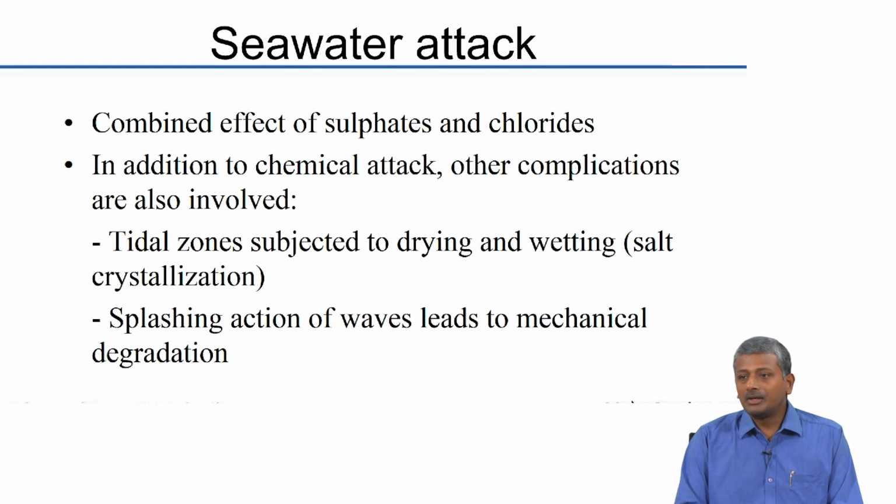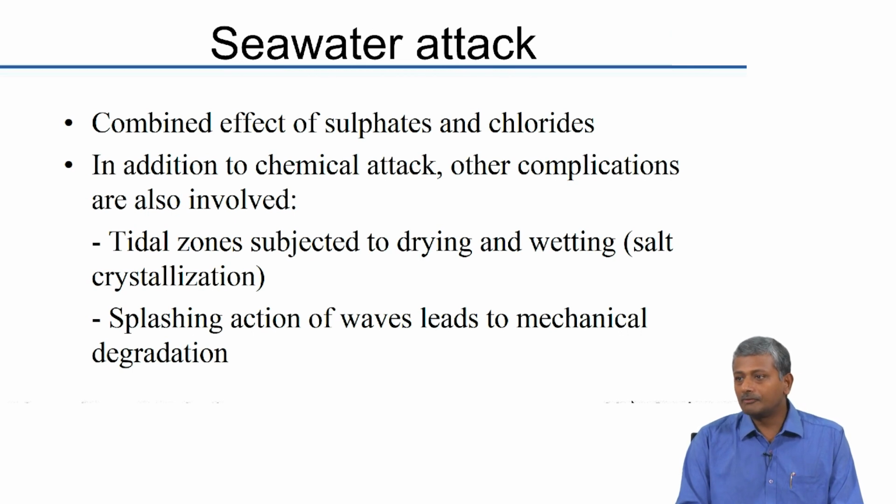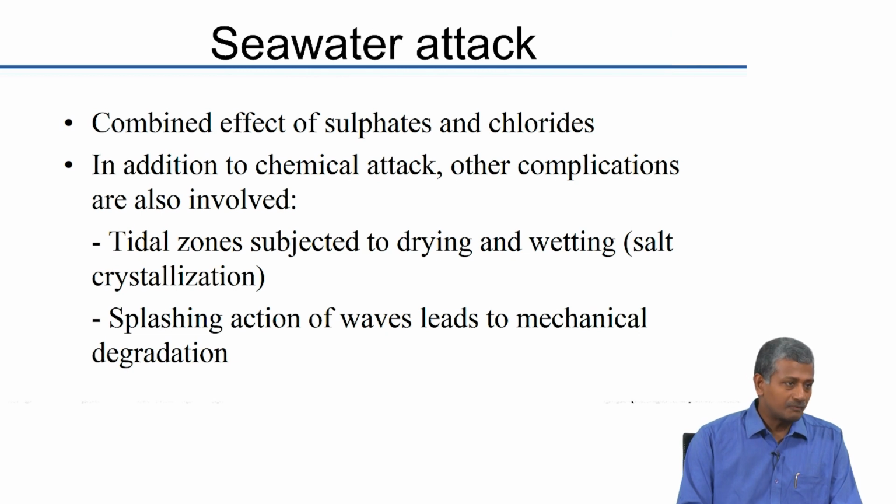And we talked about the dichotomy of offering protection against sulfate and chloride earlier, right. We talked about the fact that for sulfates we need cements that are low in C3A because you are primarily addressing the issue of ettringite formation, and for chlorides having C3A is an advantage because it tends to bind the chloride ions. So, you do not have the problem that you commonly see with sulfate related exposure.